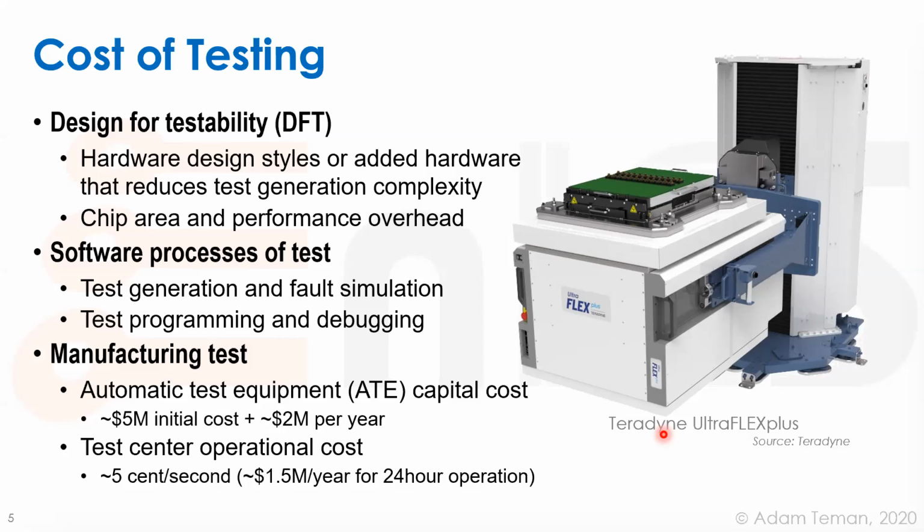So we see that testing is very expensive in the manufacturing of chips. What really matters is the testing cost per unit. Eventually, when you manufacture, you figure out how long your test will run to test a single unit, and this is a component in the cost of manufacturing, and this is the biggest concern: how much will I pay per unit extra for testing? So the motivation to make the tests as short as possible is very high.